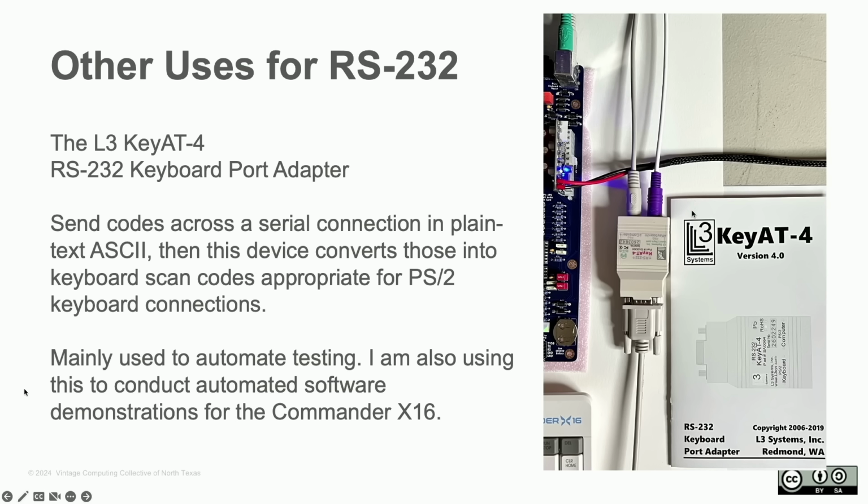You can basically automate the keys you want, and they're usually for automated testing. You write these little scripts, and I want the keyboard to type this, and you communicate it through RS232, and you can set the tempo, how fast you want to type. You can do special Control-Alt-Delete and other shift keys and modifiers. So that's an interesting use of RS232, that I was using to reboot the computer. I set it to reboot every 5 minutes. It's not cheap. It's a couple hundred dollars or something like that, just because he probably doesn't sell a whole lot of them.